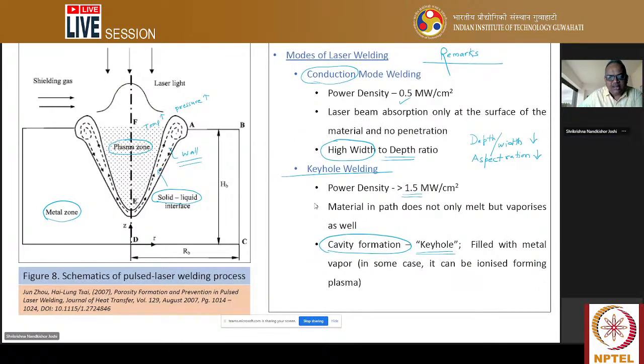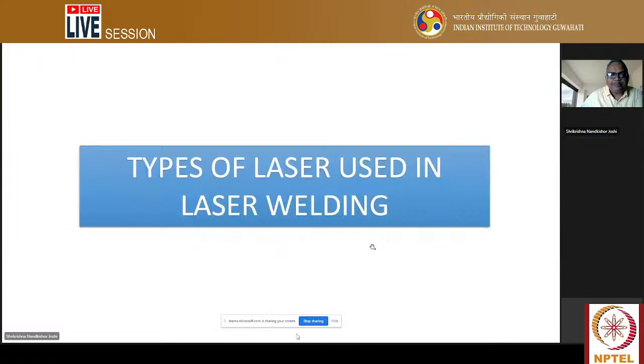It's a very useful and important welding technique to join two parts which have significant thickness, because in laser welding it's very essential to have uniform welding across or along the thickness, because many a times the laser is working at a surface level, superficial level. It doesn't go in depth. So how can we join considerably thick materials, that we have seen.